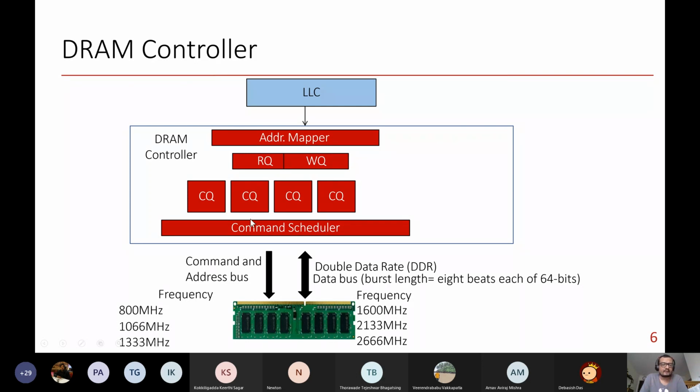But finally, a simple logic that can be utilized here is, as long as I'm getting row hits, I can start picking that particular command and then I'll schedule that. Okay. So once you schedule that particular command, it goes through this bus, which is called the command or the address bus. It is unidirectional. You are just passing that command and the address, and the kind of operations that we have been discussing so far, like activate, pre-charge, and so on.